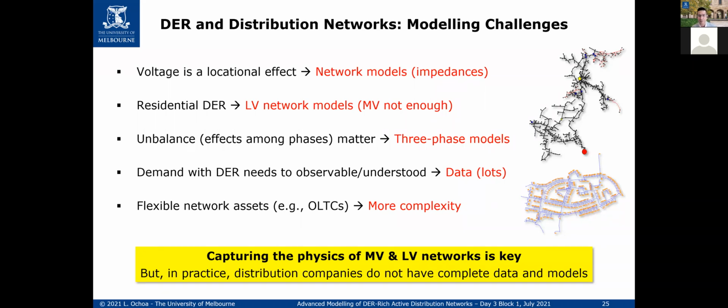I wouldn't say accurate, because it's very, very difficult to have 100% accuracy. What you get are the values from the manufacturer. Everyone believes that this is the impedance, and then suddenly there have been some changes because no one measured exactly what was happening there in the ground, and perhaps they used another conductor than what the database says. So you will always have errors, but still, if it is pretty decent, that's good enough.